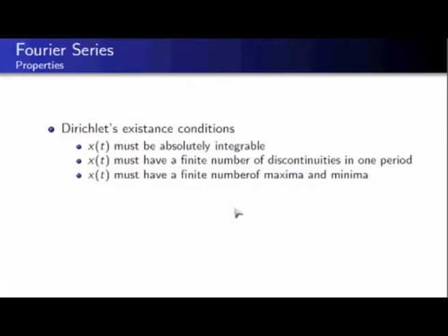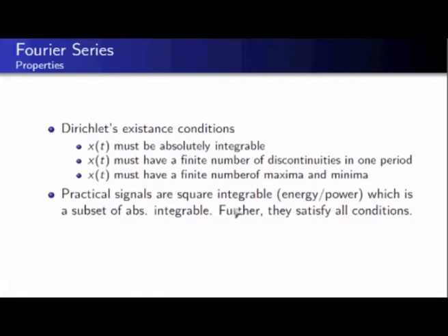If you leave it to me, most of our signals satisfy Dirichlet conditions. We deal with ordinary power signals, we deal with signals that do not have infinite number of maxima minima, do not have infinite number of discontinuities. So we have well formed signals. These are the mathematicians trying to really understand in what sense they are equal. So they are the ones who come up with all these existence conditions. I am saying that practical signals, the signals that we electrical engineers are called to work with, they satisfy Dirichlet conditions without any problem. So they are square integrable, they are energy or power signals, and they satisfy all these conditions. So we don't really have to worry about this.